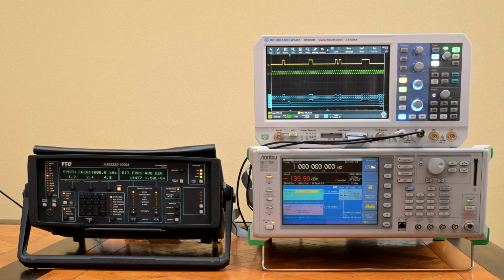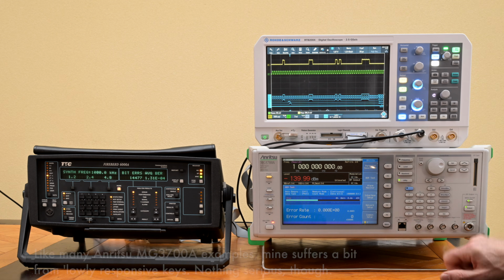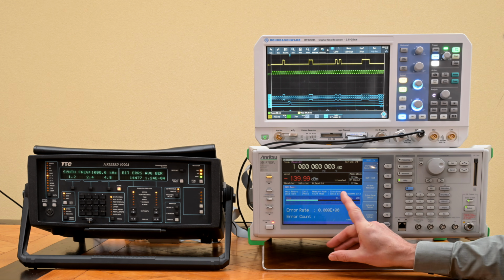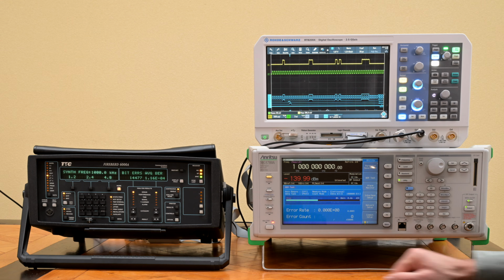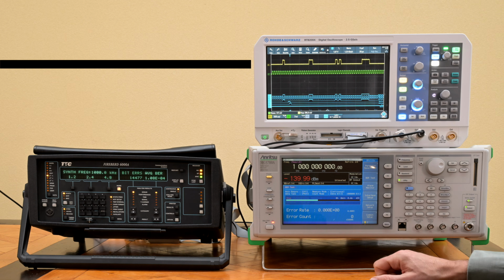So let's see if we can configure the Anritsu in the right way. I've done other videos on the Anritsu itself, and even some that look more into the bit error analysis, so I'll just quickly try to get everything to the right setting. I have to get into the utility menu, then the BER test menu, and I think I have most of the correct settings here. I don't need resyncing, I think, continuous mode. Data type is PN15. That's important. You don't need to know the speed because there's a clock coming in, so it will get it from that. But we do need to set the right type of sequence, so that is set to PN15, and this has to be set to PN15 as well.